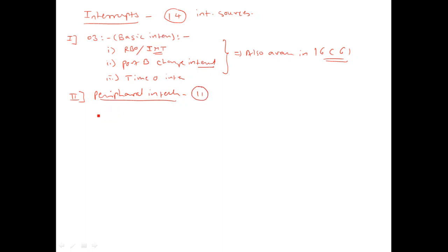So every section, every functional block, has its own interrupt. Just now we have discussed that timer 1 has its interrupt. We have seen timer 2 has its own interrupt. There is an A to D converter, we will discuss that later, so the A to D converter has its own interrupt. There is a PSP, parallel slave port, port D. It has its own interrupt. In this manner you may count the number of interrupts which are available, and that comes out to be a total of 11.